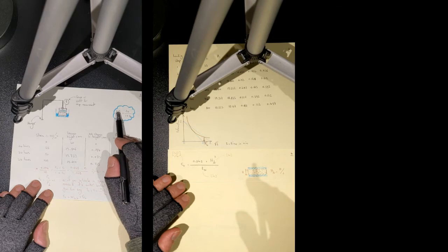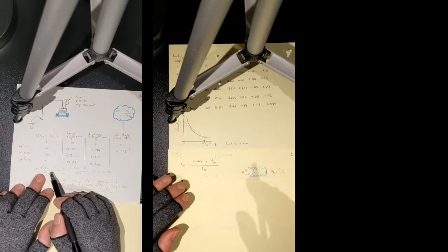So you have your initial void ratio, and you can determine your delta e, or the change in void ratio. I'll put an asterisk here. Let's see how and where I got this 0.16. Delta H in the first step of loading is 0.194, divided by H naught, which is the initial height of the test specimen, 20 millimeters, is equal to delta e.